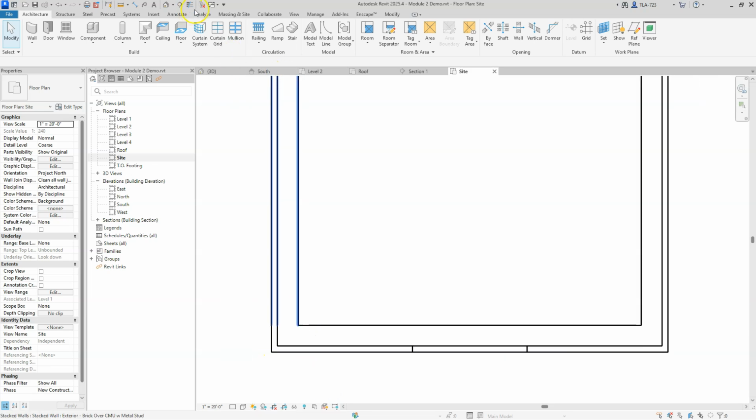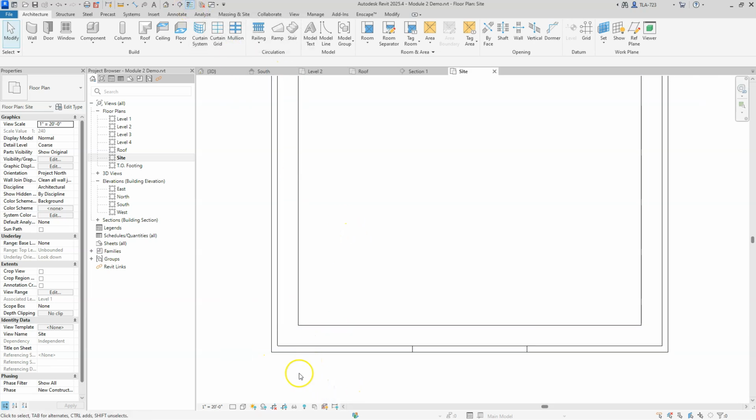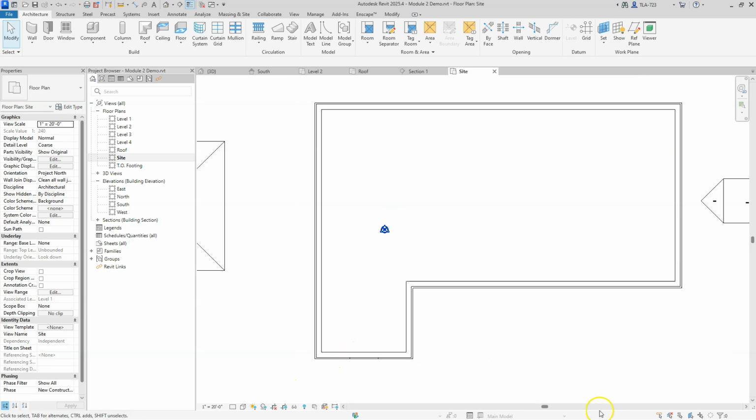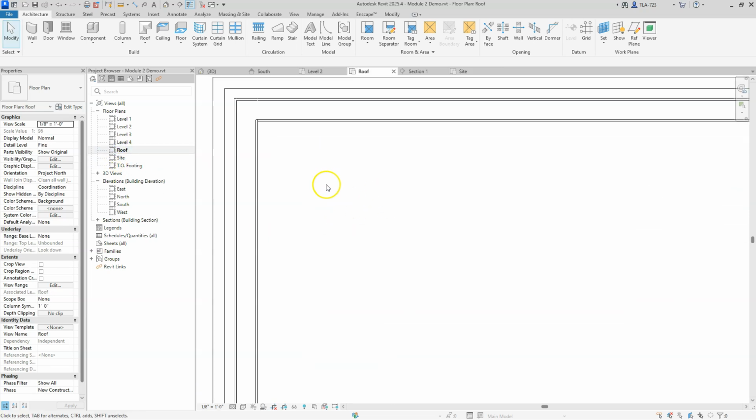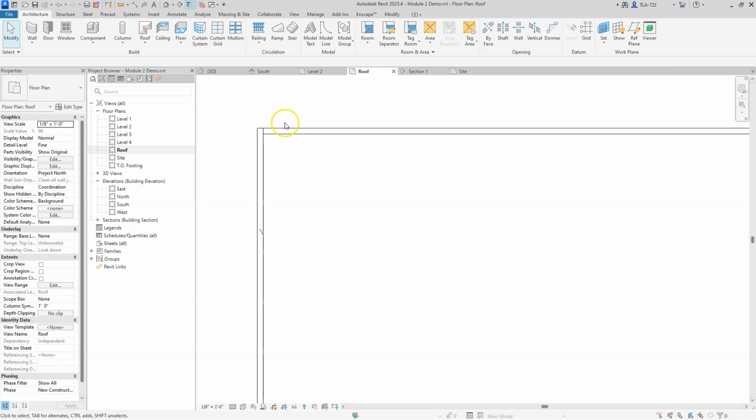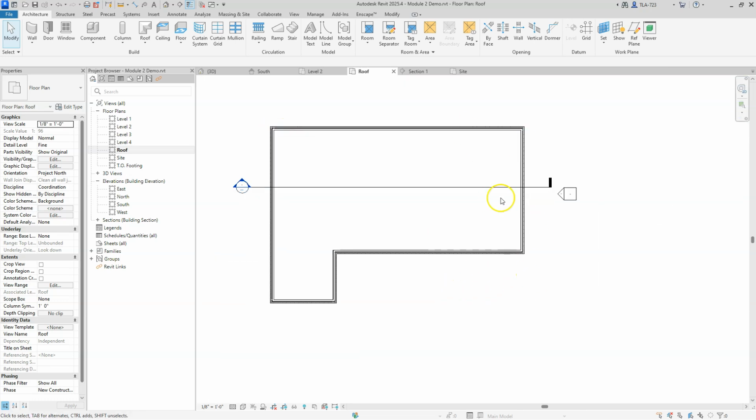Today we're talking more about how to use Revit than how to strategize exactly how we want to do a roof. Let's go back to the roof level for this so we can see the edge of our roof back in here. But the way we're going to do this is we're going to divide this roof up into 3 distinct areas, each one sloping toward the center. Okay, so we're going to do that by creating what we call split lines and low points.